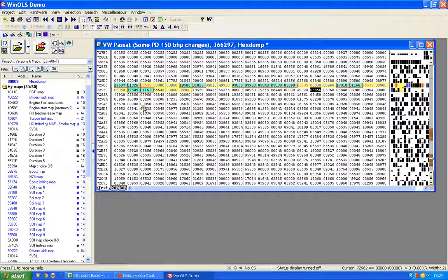Or maybe I disconnect the vacuum pipe and plug it, or maybe I leave everything alone but I put a blanking plate in the EGR. But there's a whole load of things I could change which might well cause these codes to appear. And so obviously what I do now is I drive and see, do they appear or don't they? With a little bit of luck, and I've used this system before, the codes will now not appear because I have now switched them off.